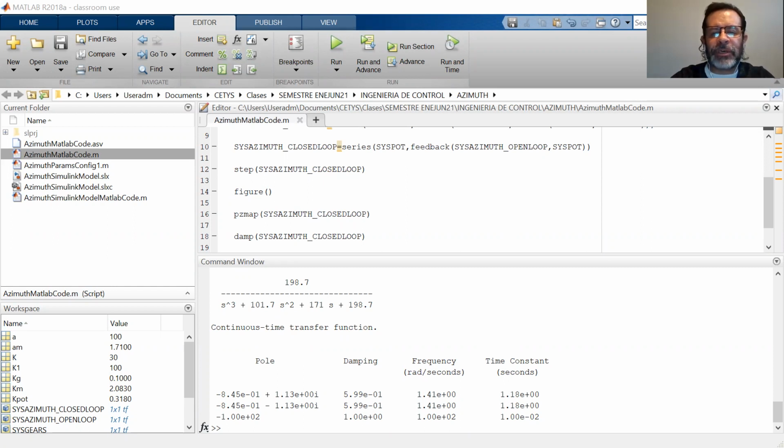The answer to that, I'm sorry to have to give, is that it depends on the system. Remember that we're talking about this huge antenna. If you're tracking an object that's moving slowly, you really don't care if the antenna moves slowly as long as it's precise. But if you're trying to track a quick object, maybe you want a quicker reaction, even if you sacrifice a little precision or overshoot. So it's always a trade-off between one and the other.